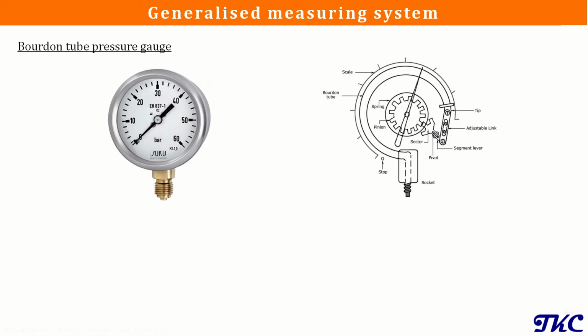Now here is how this pressure gauge will look from outside, and here we are having the internal arrangement, or the internal elements, that we are having inside this pressure gauge. This one consists of a Bourdon tube, which is an elastic member, or you can say a flexible member, and it will be acting as a primary sensing element. So that tube we are having here, this one is the tube.